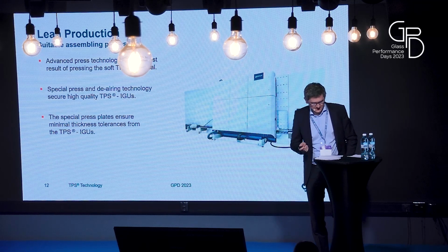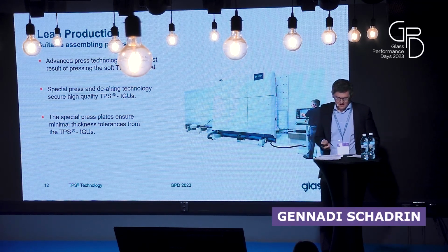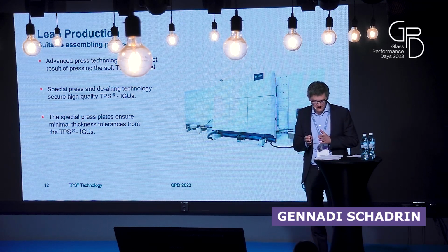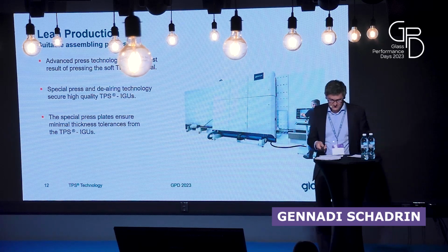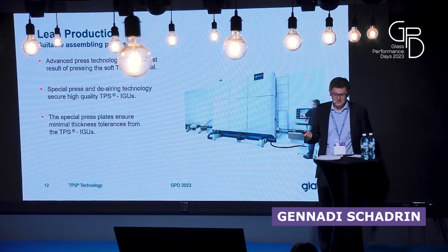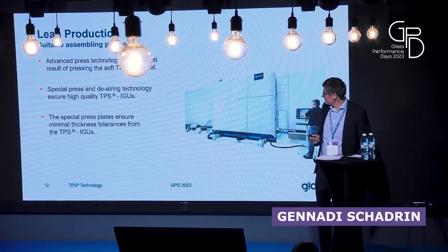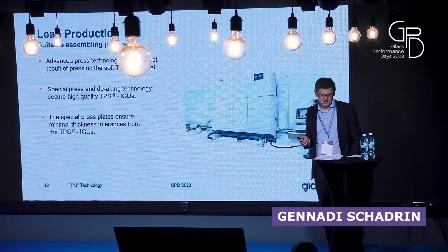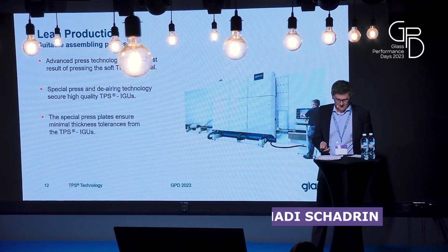So during the pressing and gas filling, it's mandatory that the air can be released and the pressure can be controlled very well. Otherwise, there will be an overpressure in the unit, and the material does not adhere very well. So the final quality will not be as good as it could be. From our 30 years of experience with this technology, we can clearly say, as long as these conditions are considered, a very smooth production is possible with a fully automated process.